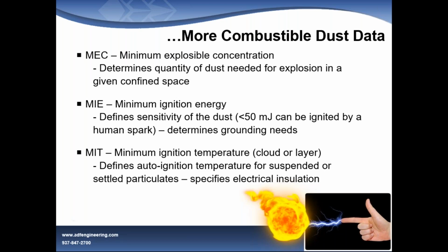Other testing that you will need that I certainly would recommend, one is the MEC, the minimum explosible concentration. This tells you how much dust you need in a given volume before you need to worry about the potential for an explosion, because another option you have is to operate below the minimum explosible concentration. That's like handling a flammable liquid where you want to run below the LEL of a vapor. It operates in much the same way. You can operate below the minimum explosible concentration, and that's a way to deal with it.